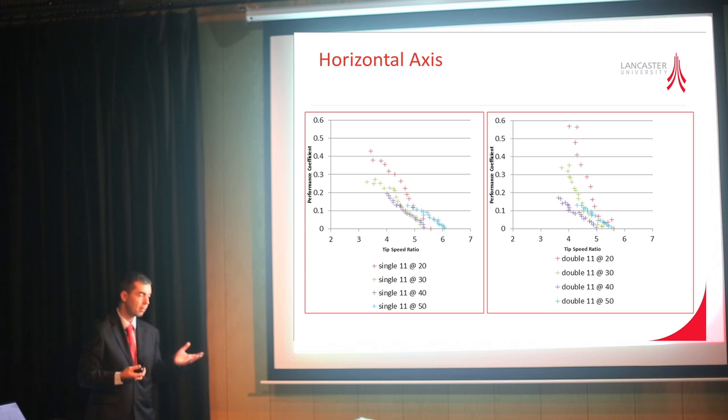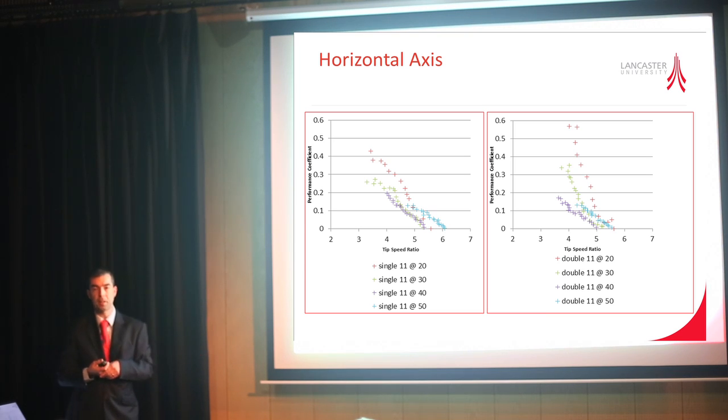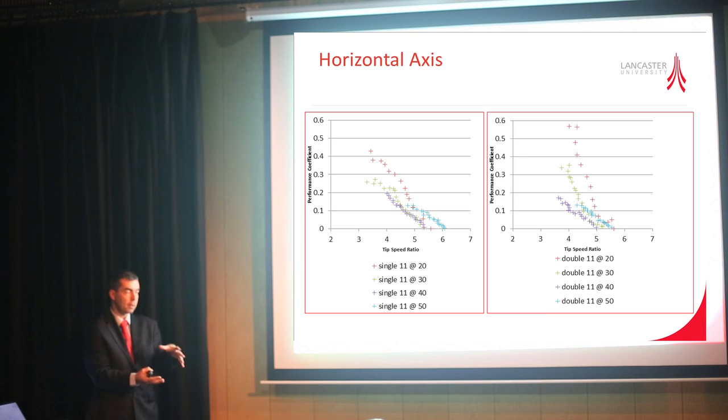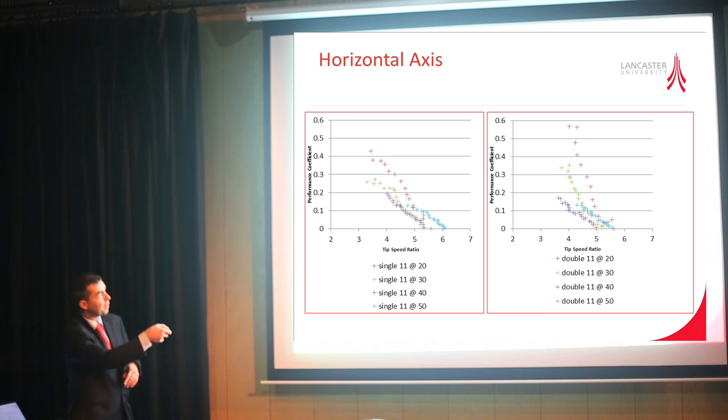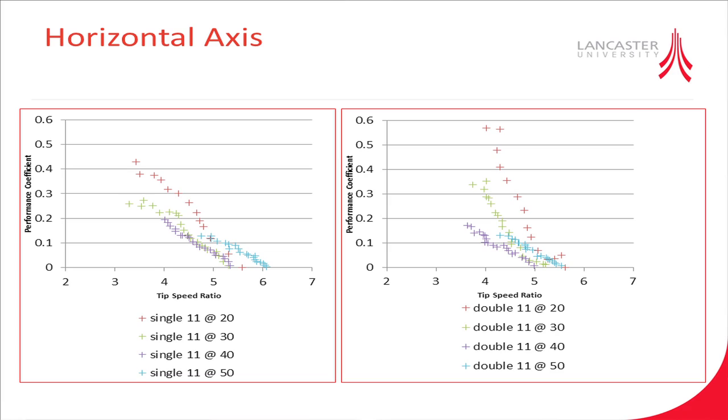There's a limit, supposedly the Betz limit of 59%, so we can't expect to get over 59% efficiency. That assumes an ideal expansion of the water, which is somewhat limited in the tides by the seabed and the water surface limiting that expansion. So theoretically, we could go beyond the 59% Betz limit in terms of energy extraction. You can see here that for the low speeds, we're certainly performing a lot better than the single blade, but perhaps for higher water flow speeds, it's not quite the same.